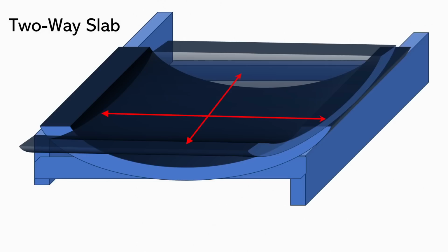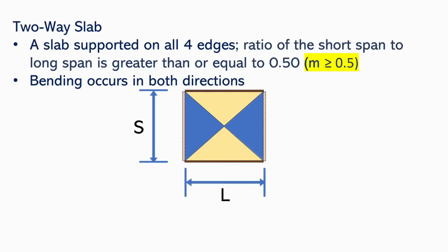Now, sir, what is going to change if two-way yung slab? Yung mag-change is yung tributary area. Now, di ba, if one-way slab, we will only consider the adjacent slabs and then we will take half of that slab. However, dito, sa two-way slab, ito na yung tributary area natin. Instead of tig half ng adjacent slab, we will actually consider this triangle.